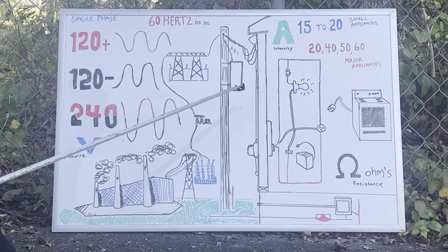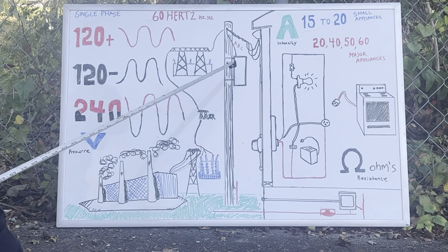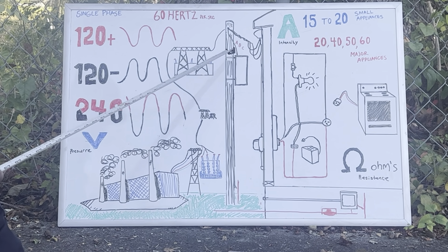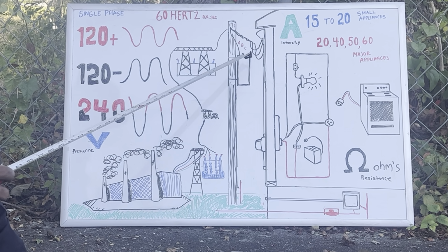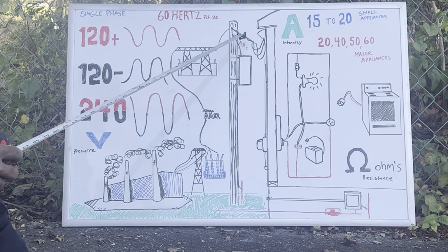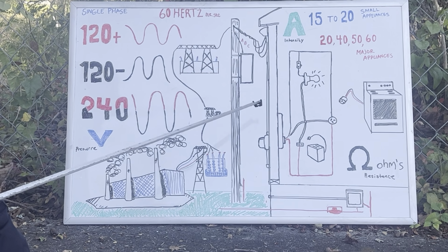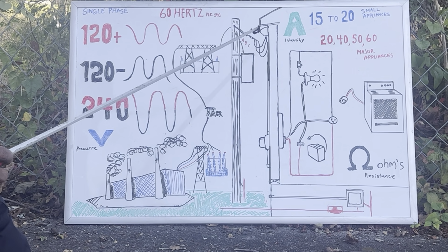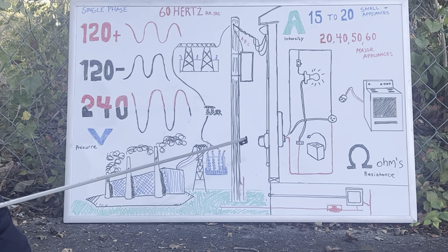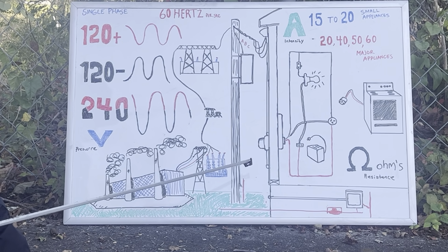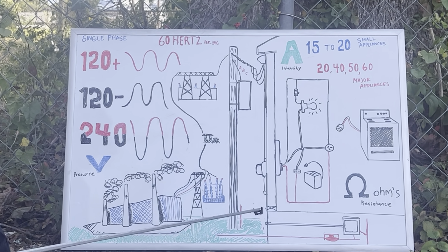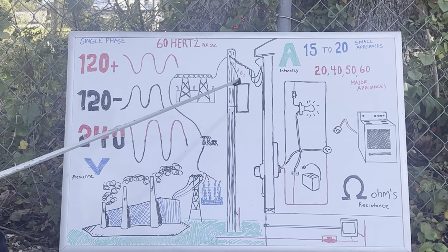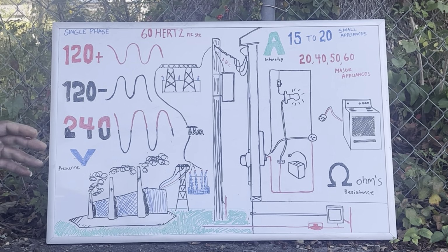The way you make 3 voltages would be to put A with C, that's 120 volts. You can put B with C, which is basically a hot and a neutral, and that's 120 volts. But then you can also put A, B, and C together, which would be 2 hots and a neutral, and that will create your 240.